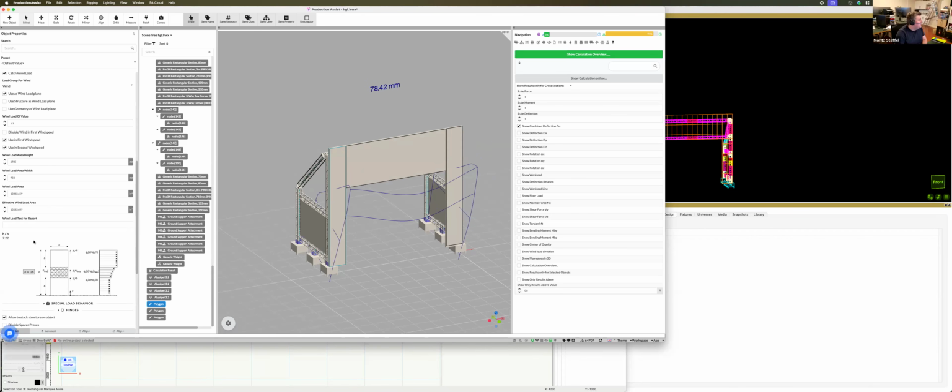So for example, in here, because the structure is so high and doesn't have so much width, the actual wind load that will be applied is based on the height. There's a specific setting on how to do it, and then it will be applied like this. On the same thing, there is a dialog for the bigger structure in here. And you see, because the width is way bigger, independent of the height of the structure it will always get the complete maximum wind load on the full area. So this was one of the changes that we've been doing.